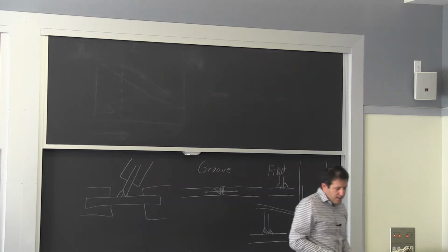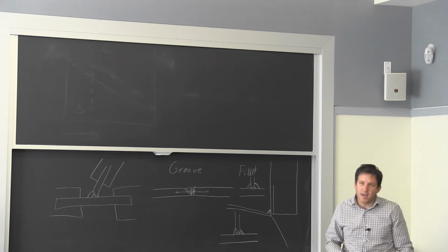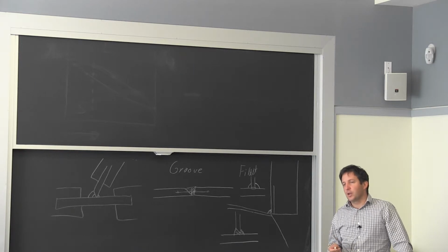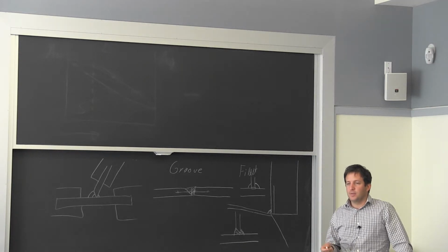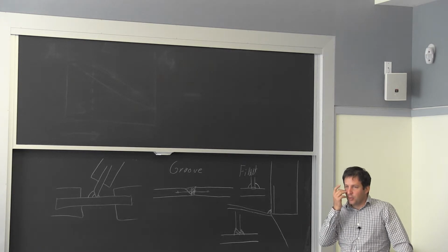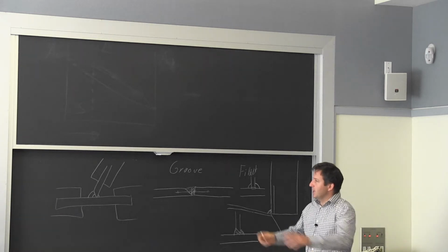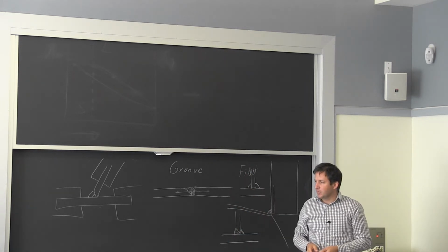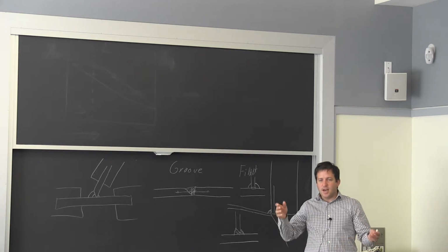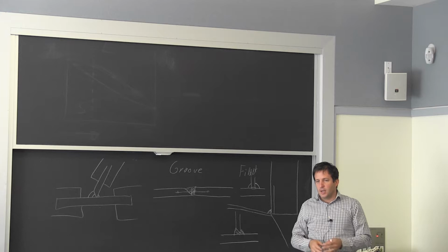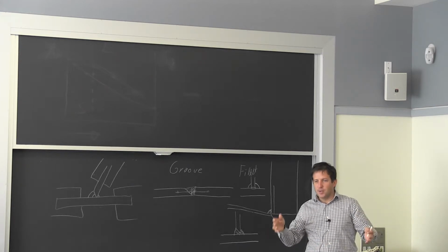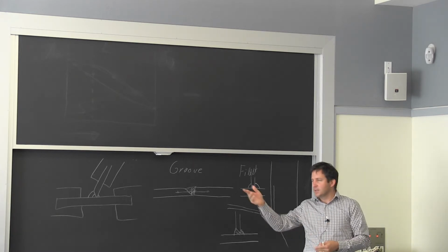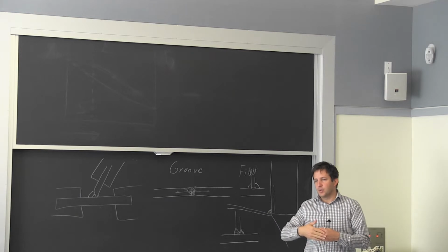I've seen cases where field welding was not desired. Even a lot of times for building erection, they'll still bring the welder because they don't have to go out in the field and drill holes. But say they decide no field welding. A lot of times, if they have big braces, I'm thinking right now of the nuclear waste treatment facility I was working on, they needed a lot of braces for seismic loads. And they didn't know exactly how square the building was going to be. So these braces came with the attachment plate, essentially a gusset plate, already welded to the tube.